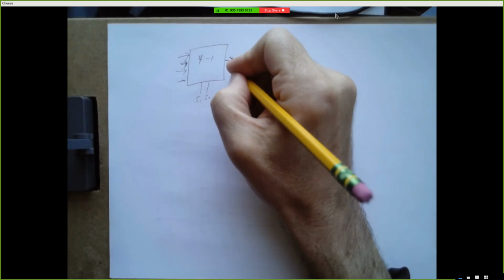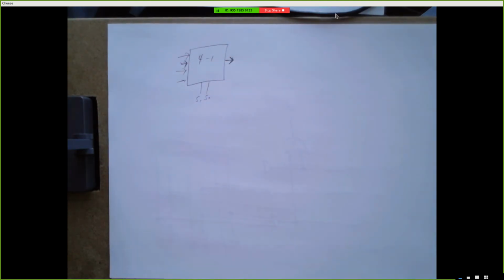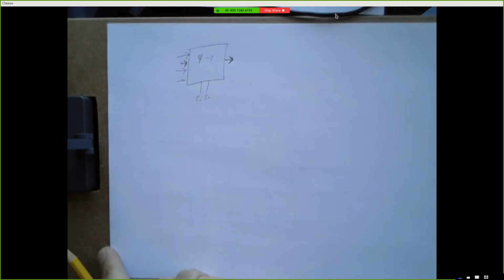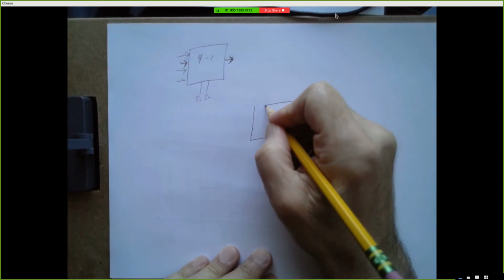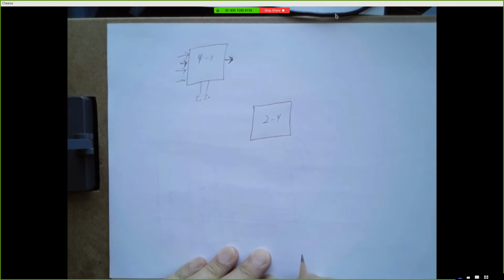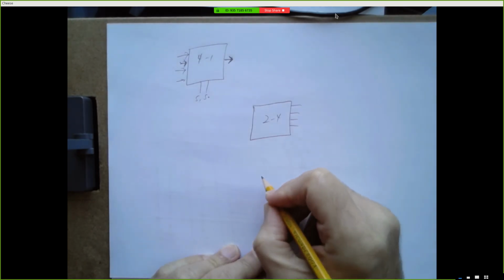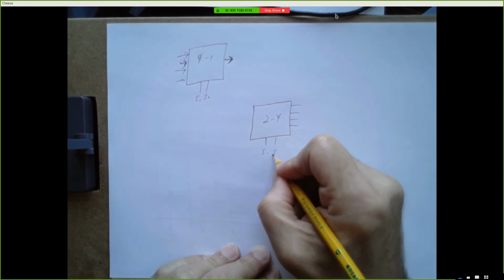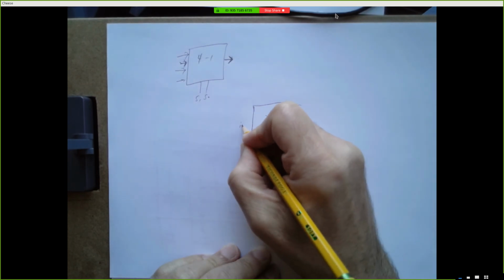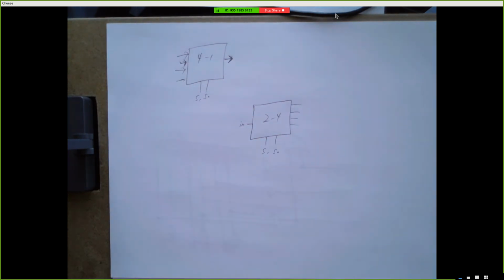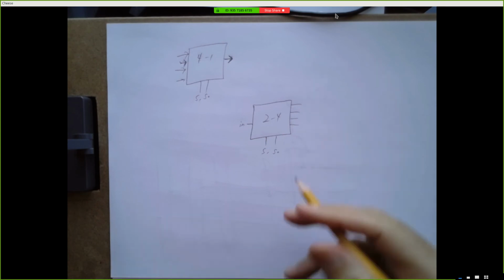Okay, and so this is like the demux from the earlier homework question. Depending on the value of these, your output comes from one of those 4 inputs. Okay, the demuxer would basically choose one of 4 outputs, and it would send this input to one of those 4 outputs. And the question is, what should the other outputs be?